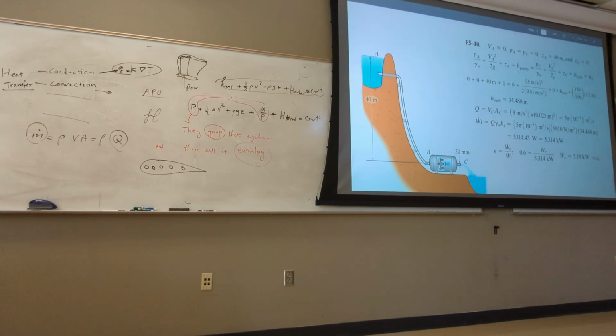Now when you get the value here, when you get H of turbine, you should not report that number. Why? Because this number you get here is in what? Meters. What is the question asking you to get it in? Watts. You have to compute your flow rate and gamma and multiply by flow rate and gamma to get the power, the watts. Do you see that? It's not really hard to forget to do that.